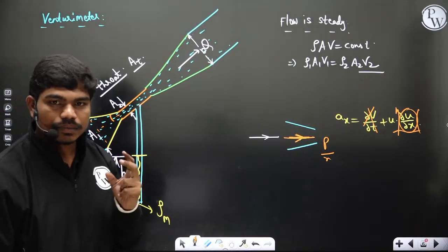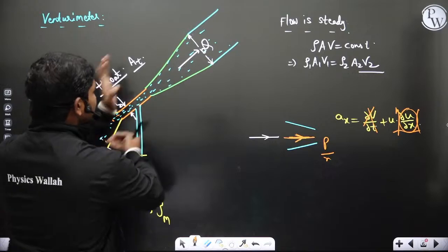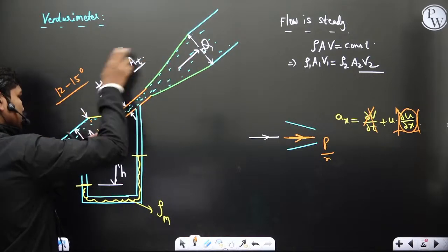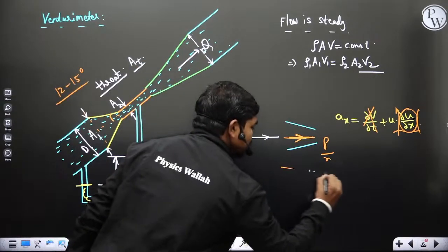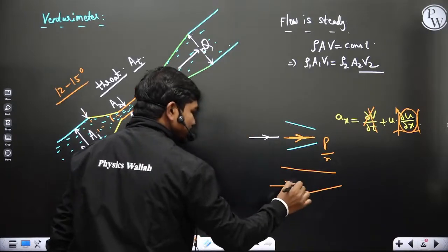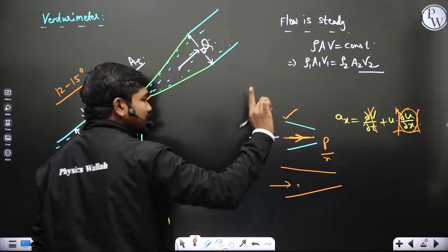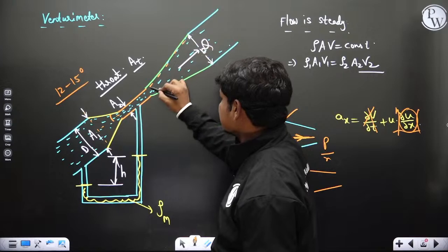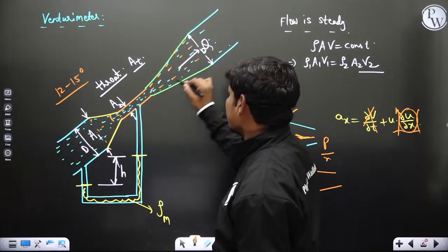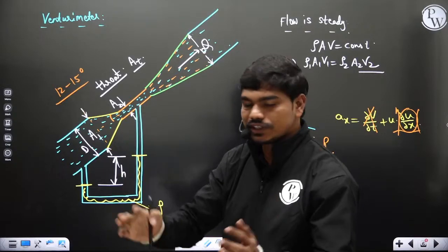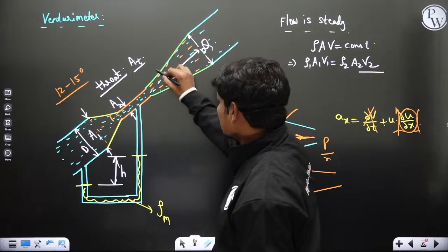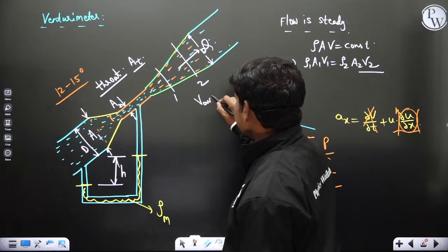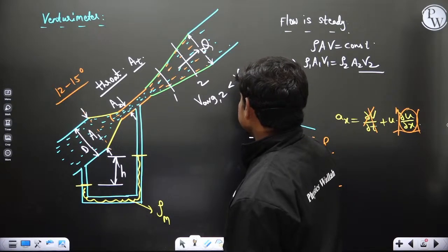And the second point here is, let us suppose you have connected the nozzle in this direction. This particular part, the diverging cross section, if it comes to this side, it becomes converging, and you will have a lesser cone angle part in the fluid, so this facilitates the flow less as compared to this case. Second, in this downstream direction, normally the fluid decelerates here, correct? Of course, the continuity equation still holds good, but if you compare the average velocity at the first and second sections, V average at the second section is less than V average at the first section, correct?